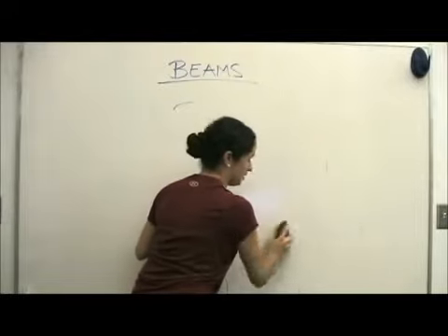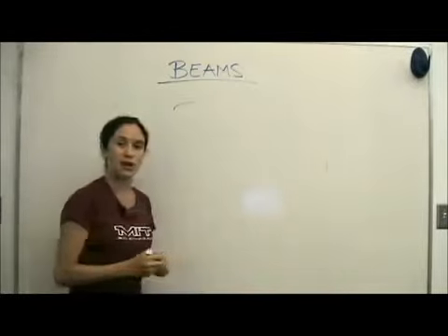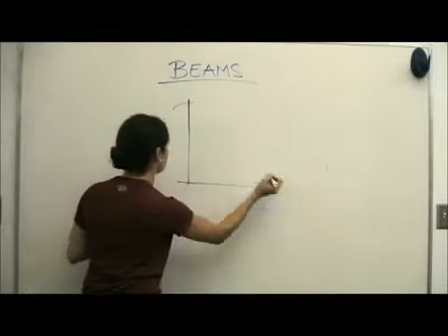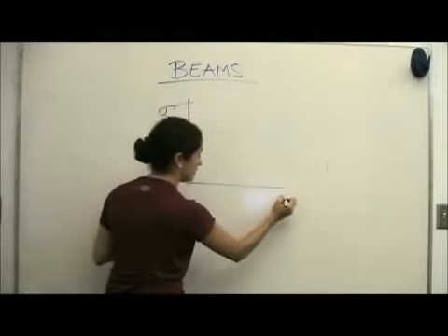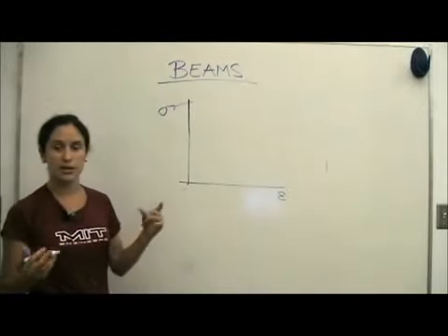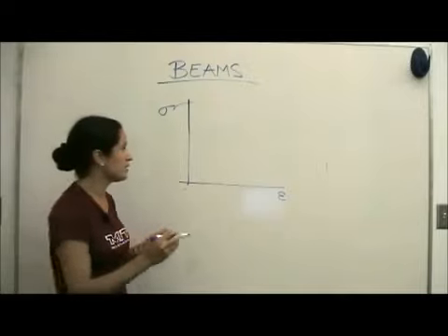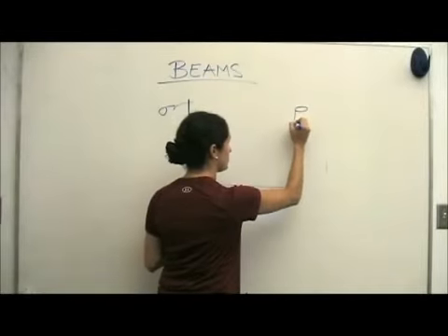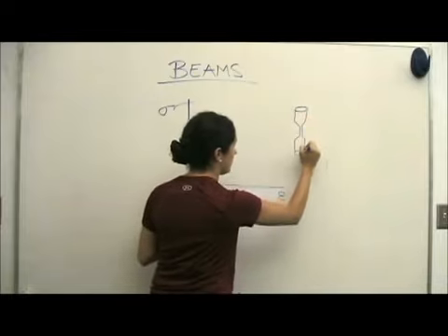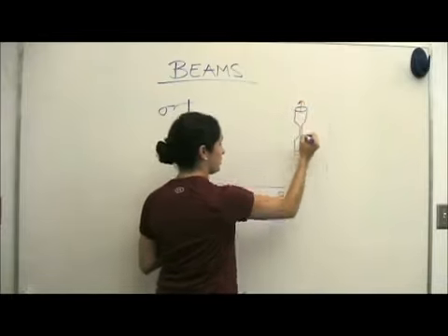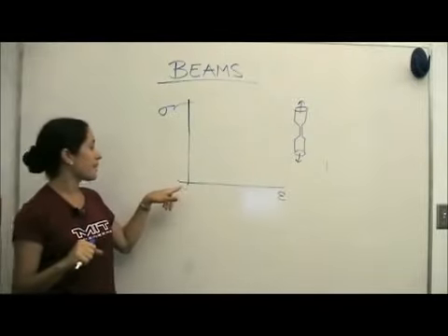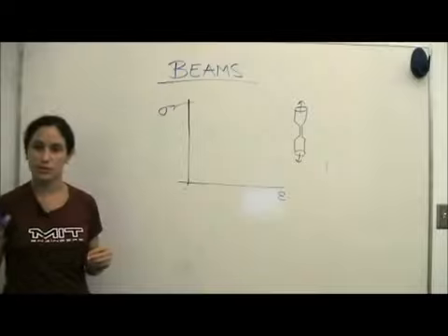The best way to understand the Young's modulus is to look at a graph of the stress versus strain. So we're going to have a graph here where we're going to have stress on the y-axis and strain on the x-axis. The way these graphs are collected are actually in machines that test samples. The samples usually look something like this, where there's a necking section. And what the machine does, it pulls on the sample. It measures the stress that it needs to pull on the sample with, and then records how much the sample deforms under the load.